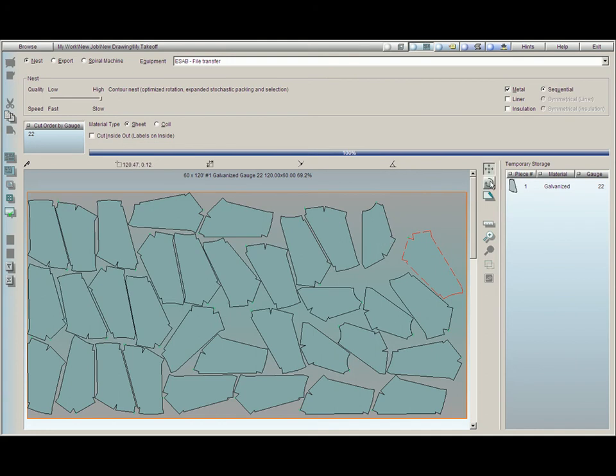Now when you're using the move key or the rotate key, it's important to know that you don't have to do things freehand. For example, notice here I'm going to click on the rotate key. I can select the piece I want, and you will notice up here that I have an angle. If I decide to put in, say, 45 degrees and hit enter, it will rotate it every time I hit enter at 45 degrees. You'll notice that if I do have a blank that is going to overlap another blank, PractiCAM will mark it with a red dot. If I just move it out of the way, you will see now that it is clear.